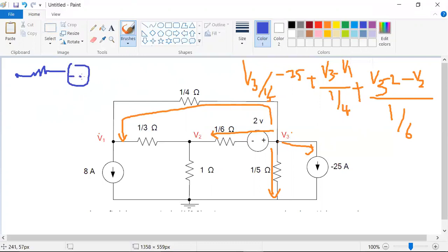This is minus, plus, and this is V3. What I'm trying to say is, without mentioning Vx, you can also write this equation directly. This is V2. The signs are very important. Here this sign is positive and negative. This sign is positive and this is negative. The resistance sign doesn't matter while you're writing the nodal equations. Always the signs of voltage sources are very important. So this is 2 volts, right? This is 2 volts. Now my current is flowing like this.